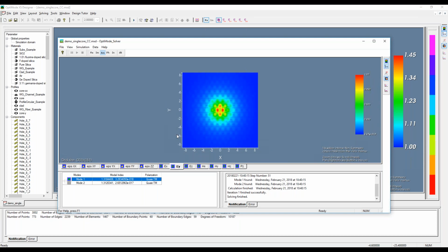So the major component here is the EY component. So that was a success. It plots it on the whole domain because usually you want the whole domain, but it's only simulating a quarter of the simulation domain, and that is very key, I think, to help with the more complicated simulations, where if you want to get really high accuracy, you want to use things to your advantage, like symmetry.